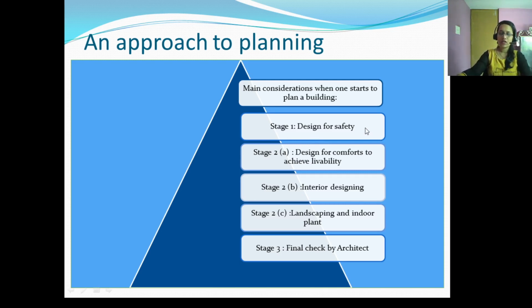Now the important decisions related to the structural design are taken by studying the site data and holding discussions with architects, consultants and clients, with reference to the site investigation report, site contours and features, soil and its bearing capacity. What do you mean by bearing capacity? It's the capacity of the soil to withstand the load which is applied to the ground. Then foundation problems, the structures, then building acts and regulations for the structural design and safety. All this comes under design for structural safety.